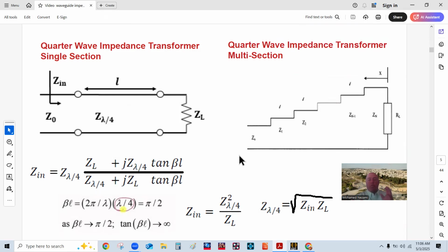And so with those two things, not the frequency, but just the maximum return loss and the bandwidth, you can figure out the order and go into the tables, and then it would give you the various sections and impedances from the source to the load.